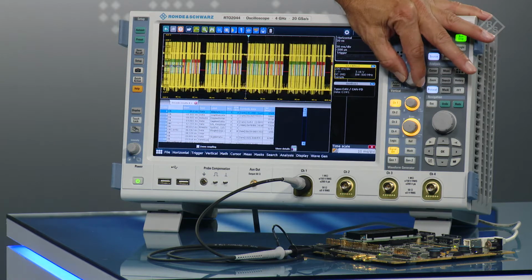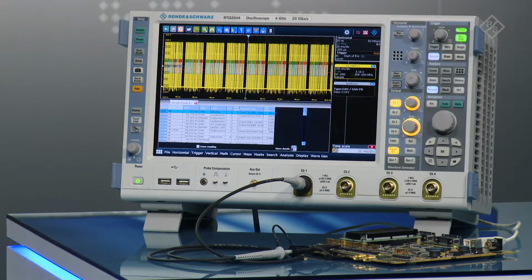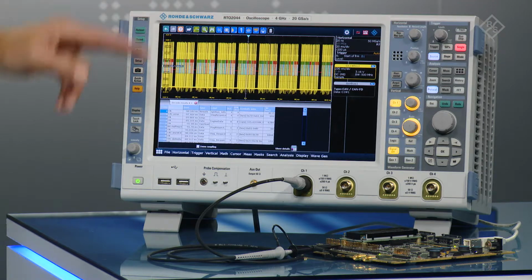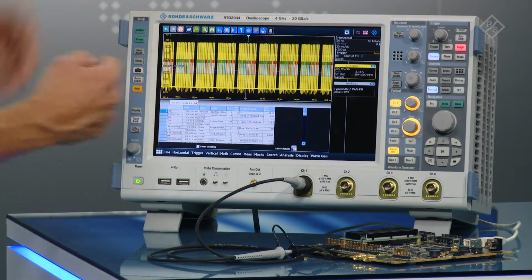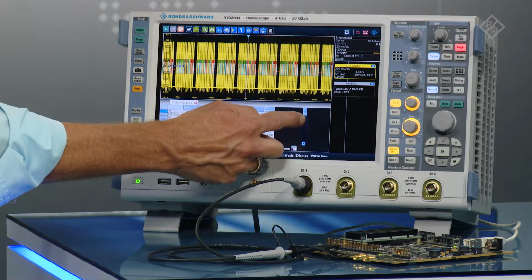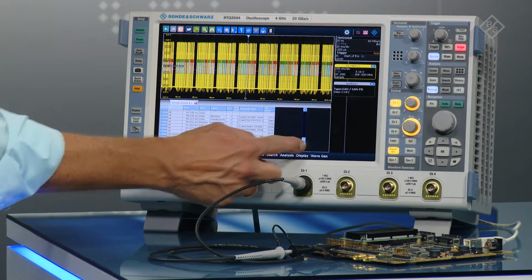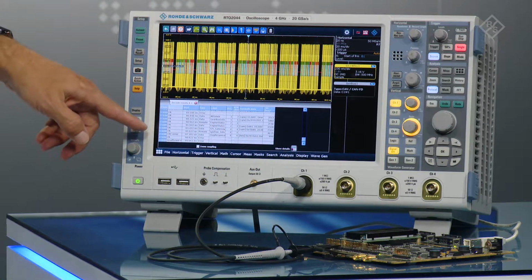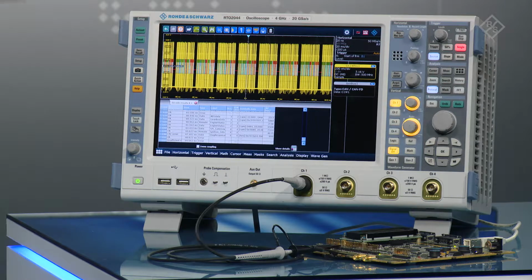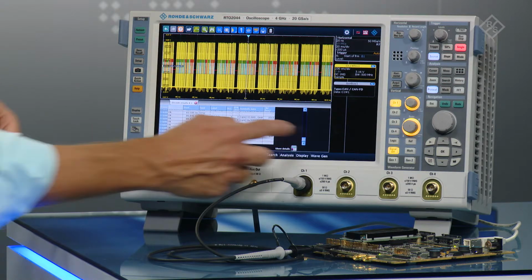So we can go to, let's say, now we are having 20 milliseconds per div, so it's a 100 milliseconds capture. You see we capture a lot of frames. I just make a single run, and we capture lots of frames. When you go through the list of the frames, you see we have captured now around 100 frames, or more than 100 frames. Now we can debug and look into that frames.